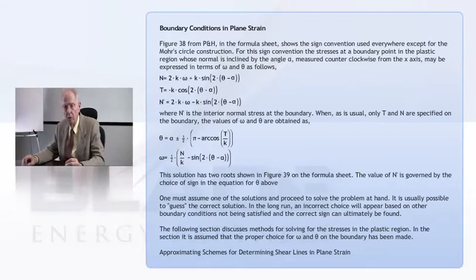You'll recall that when we write down the boundary conditions, we discovered that if we looked at a boundary where plastic flow was occurring, we could specify the surface normal stress and the surface shear stress, but we, in most problems, really can't specify the interior normal stress.